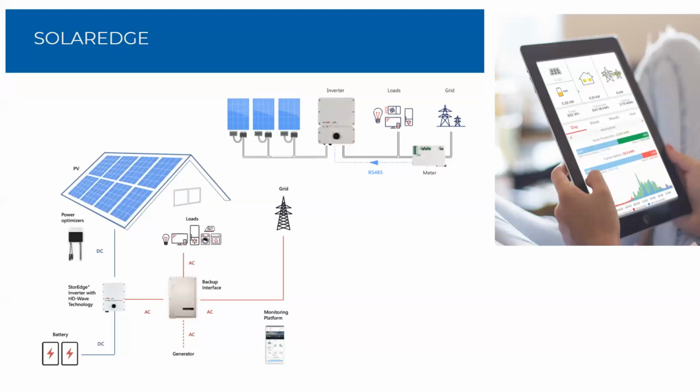Where we are today, the backup interface can have up to 3 energy hub inverters, and each of those energy hub inverters can have between 1 and 2 batteries. So SolarEdge really is posing themselves for whole home backup, because if you're having up to 3 energy hub inverters, that's plenty to power a full house to cover your whole 100 amp or 200 amp main service panel.